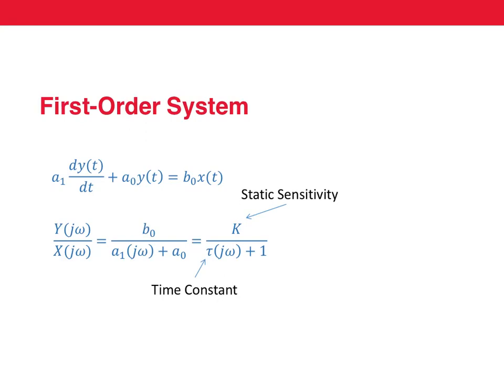But that's not the way a thermometer works, right? A thermometer doesn't work like a zero order system. So let's think of a thermometer. And here's the bulb of mercury. It looks like a very big bulb, but I think it's all right. Now, if you put it at a new temperature, the column of mercury rises up slowly. It doesn't go at the same speed at which the temperature actually changes.